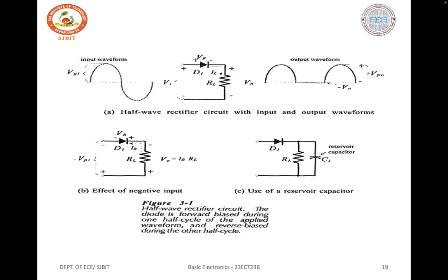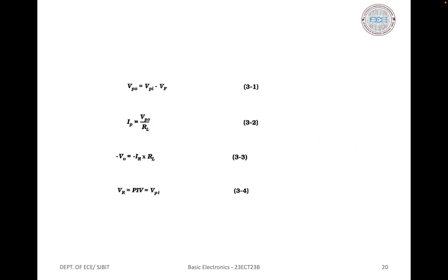It is important to note that one of the rectifier circuit output terminals may be grounded only when a transformer is present to provide complete DC isolation from the AC supply. If a variable transformer is used without a power supply transformer, a 1:1 isolation transformer must be substituted for the power supply transformer to provide the required DC isolation.